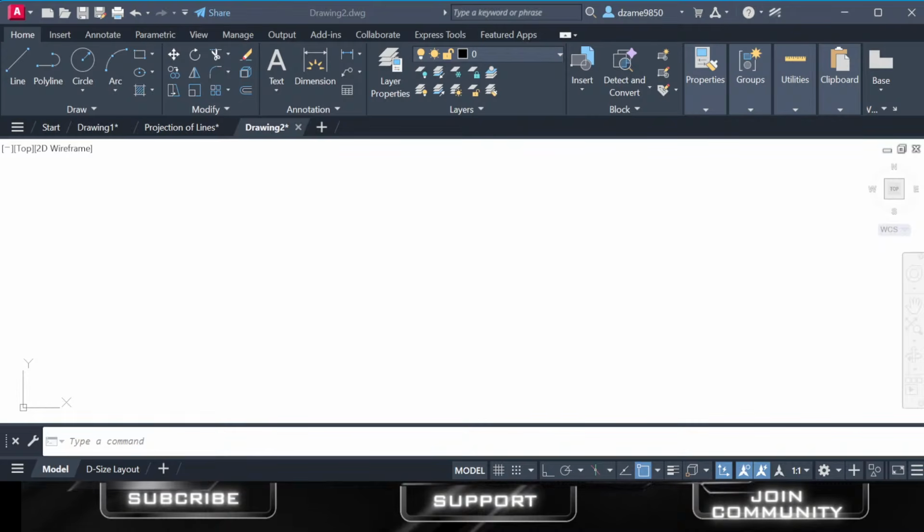Down here is what we call the command line. This is where AutoCAD listens to you. Let me show you what we call a command line. If you click a cursor here, let me just do that one so at least you're able to understand what I'm communicating to you. If for example I click here, now it's active. If I type L to start the command, let's say I'm typing a line command, it populates.